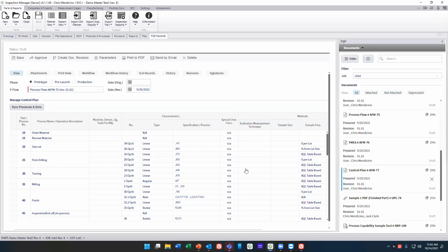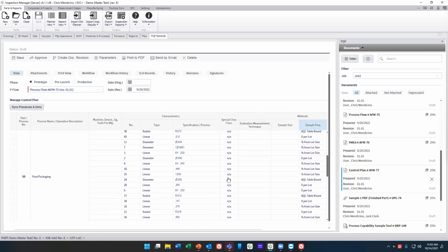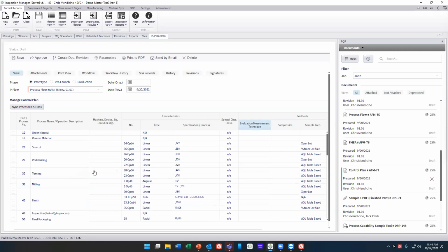So ideally, I'm not doing a lot to engage with the control plan itself as a report. Ideally, all the content is getting established back at the drawing level, like gauge categories, sampling frequencies and size and so on. All that stuff should be defined at the drawing level with those tools that we have for that. And then it gets pulled forward into the control plan.